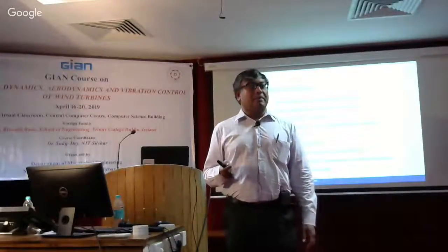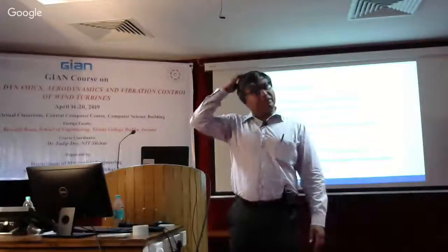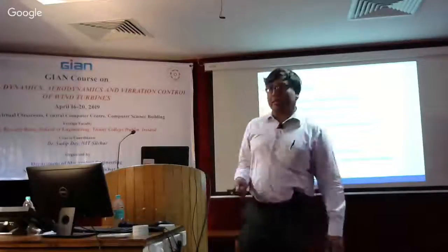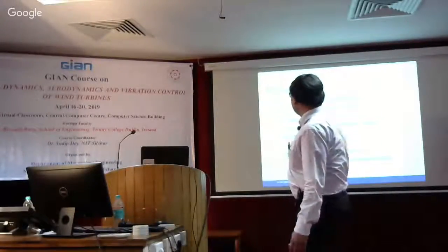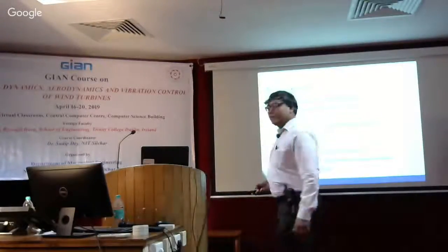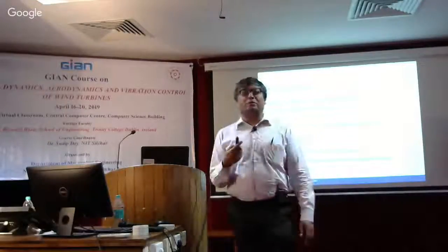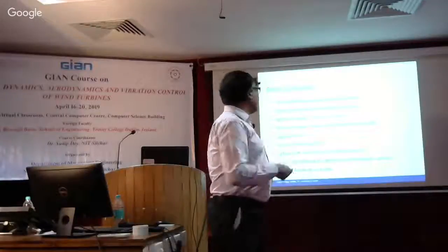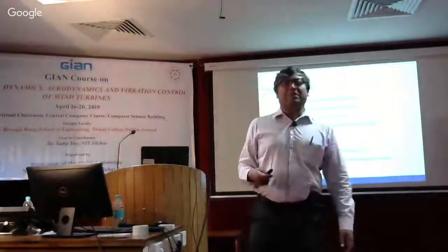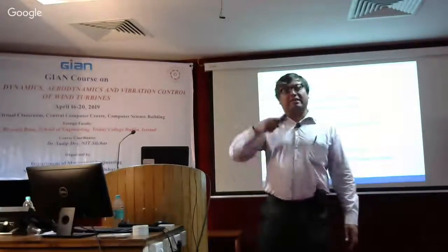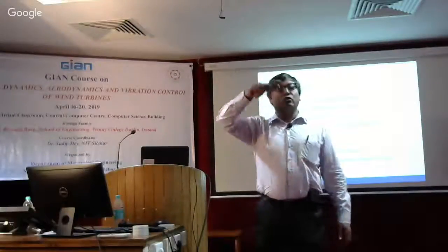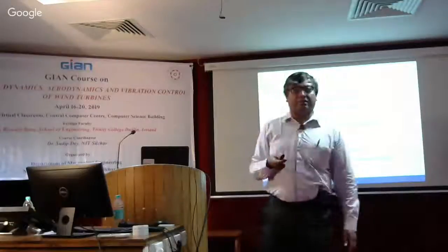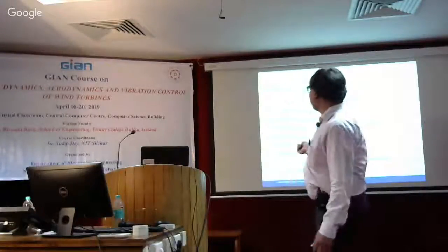But the most important thing is that we don't want to run the generator above rated condition. So obviously, that is primarily what we want to do. Also, below rated, we want to optimize the energy production. So these two things are mainly done by the pitch controller. And as you've seen, when I discussed region 2 control and region 3 control in the first or second day of our lecture, we'll look into those a bit more in detail.